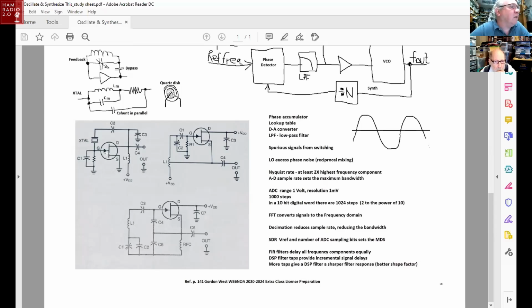And third, they have inductors, capacitors, and resistors. The JFETs don't need many resistors. There's just 1 or 2 here and there. And one of them uses a crystal. Now let's start on the top left circuit and identify where's the feedback path. Well, in a JFET amplifier with grounded sources, this is like a common source amplifier.